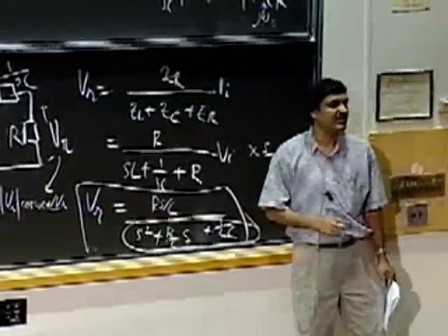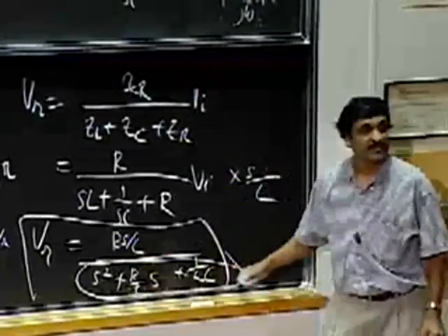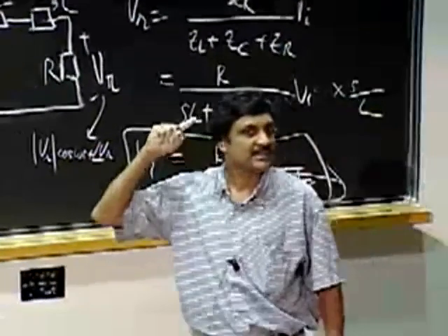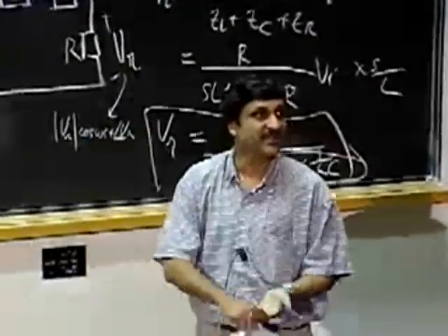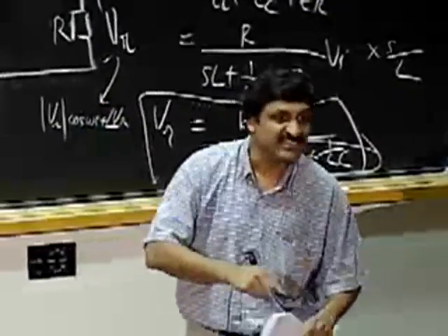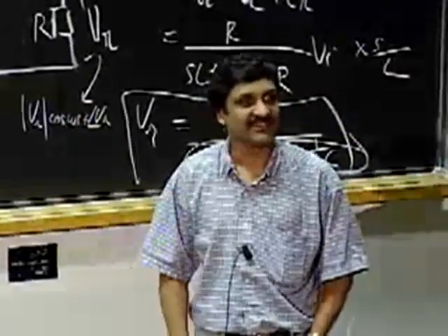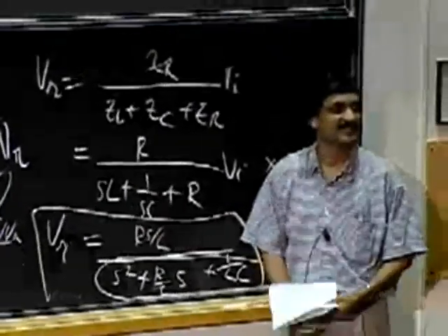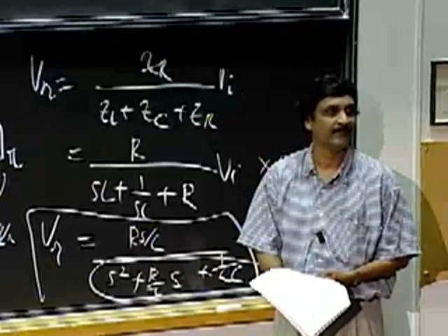Even more beautiful, and what's even more stunningly pretty here is that, remember that intuitive method I taught you about. The characteristic equation gives you alpha, omega naught, omega d, and Q. And based on those, you can sketch even the time domain response. So guess what? RLC circuits are passe now. You can just write this thing down and you're done. 30 seconds or less. Okay, no DEs, no trig, no nothing.